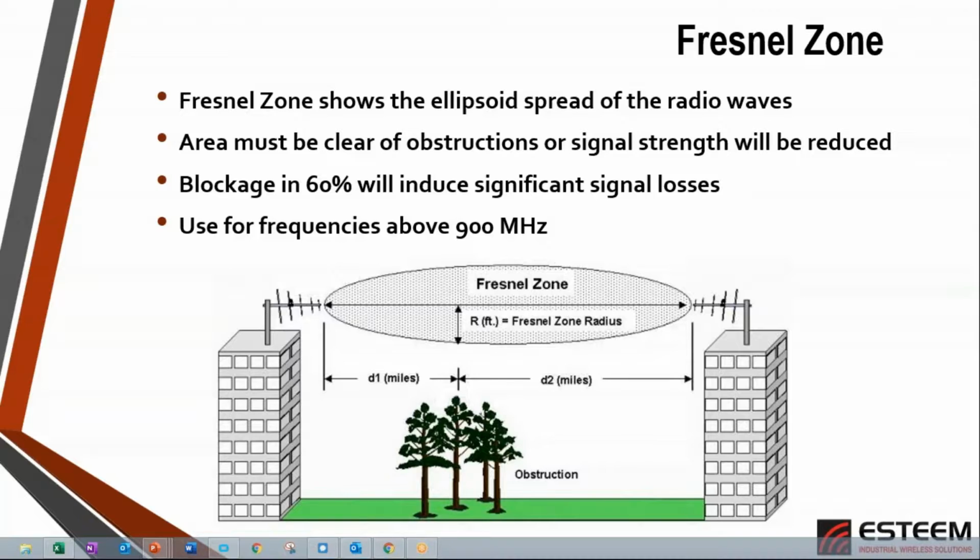Now, just as we were talking about in the first training session, the one thing that is most destructive as far as RF energy is this principle called multipathing. Multipathing means that as the RF signal travels past an antenna, if it strikes a surface, it can actually reflect back, and as it arrives at this antenna once again, it can arrive out of phase from timing and cancel the original signal out.